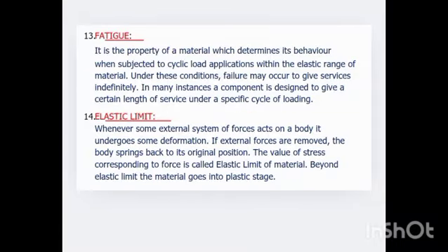Then fatigue. Fatigue is a failure of material due to repeated or cyclic loading. Even if the stress is within elastic limit, repeated loading can cause failure over time. Fatigue is very important in rotating shafts, bridges, aircraft parts, and machining operation. It's a cyclic load application in the elastic range.